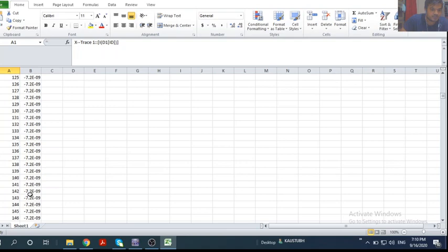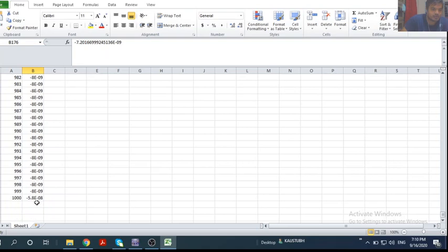You see, from 1050, this same value is only slightly increasing, earlier it was 7.1 nanoampere to 7.2 nanoampere, 7.3 nanoampere, at 330 7.4, 500 7.6, at around 923 7.9, then at around here 999 it is minus 8 nanoampere, but at 1000 you see 5.8, or 0.58 microampere, this value. Okay, so that means somehow it breaks down.